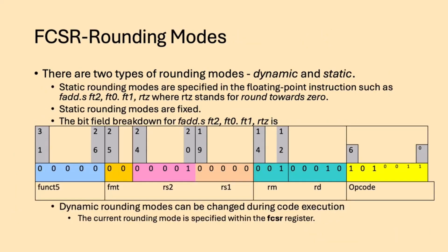So this table shows the format of the rounding modes as they are expressed in floating point instructions. We have static rounding modes. There are preferences such as round towards 0. So you can do this or you can round up. Again, we're very familiar with this type of operation. So the rounding mode itself is held within the floating point control status register. And you can see the bits that are available for this.